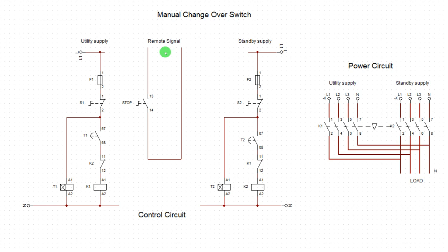Use to terminate on the switch of the genset. Okay. All right. Now, this is the stop button for manual operation of it. Now, to make it automated, on the utility side, this contactor on the utility side, we need to insert auxiliary contact. This is the auxiliary contact.